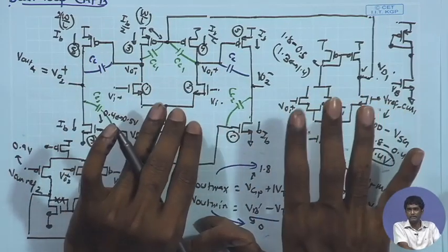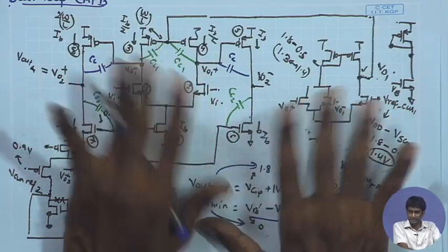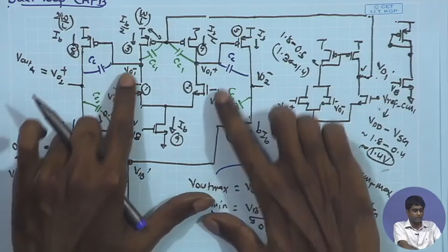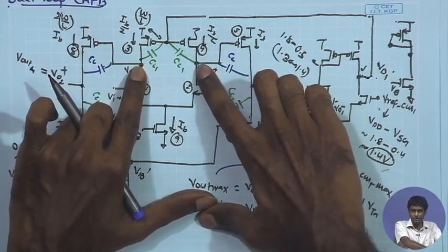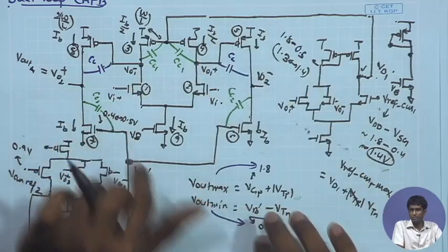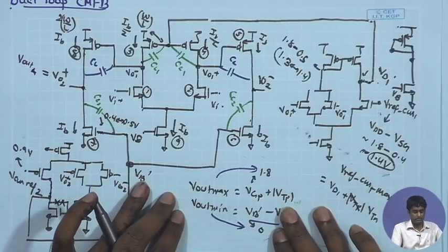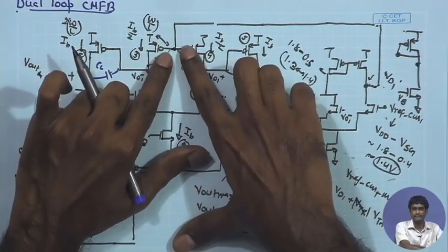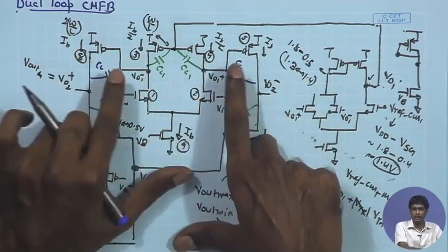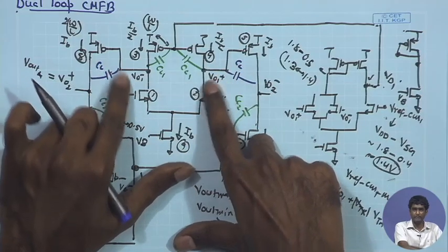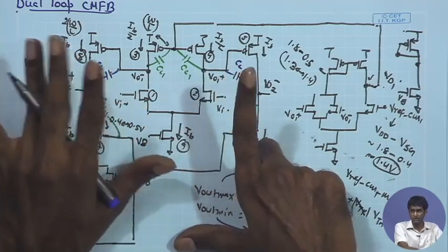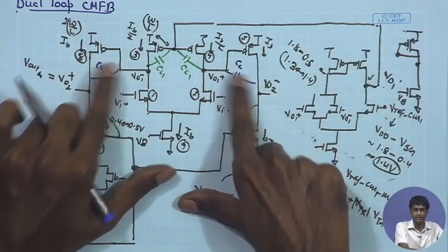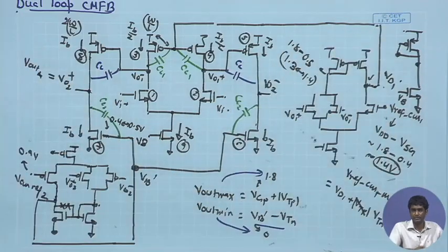But in other cases, say your supply voltages are very stable and you do not have much common mode disturbance coming in from other sources, we can afford to make the common mode feedback relatively lower frequency, and in that case you may go for larger CC1 and CC2. Then I have to make sure that the effective CC1 coming over here for the differential loop is accounted for while choosing the value of CC for differential compensation.